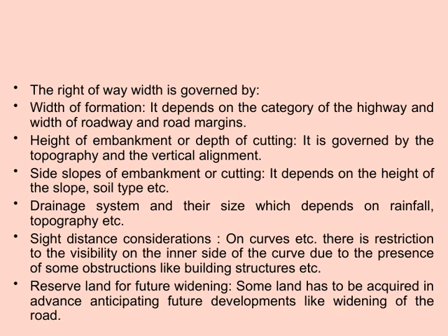The size and design of drainage channels depend heavily on local rainfall and topography. Proper drainage is vital to prevent water accumulation and erosion, so we must account for these factors when planning the land width. Sight distance considerations are another key point.